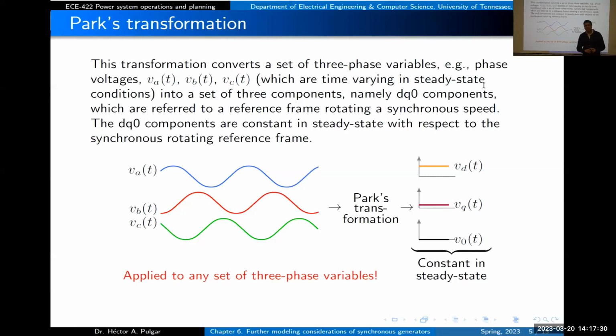That can be another whole course on disturbances, on short circuits. When you deal with imbalanced situations, we use another transformation that is the Fortescue matrix. Basically, we decompose these signals A, B, and C into positive sequence, negative sequence, and zero sequence. So zero sequence is a very particular imbalance you might have in the system.